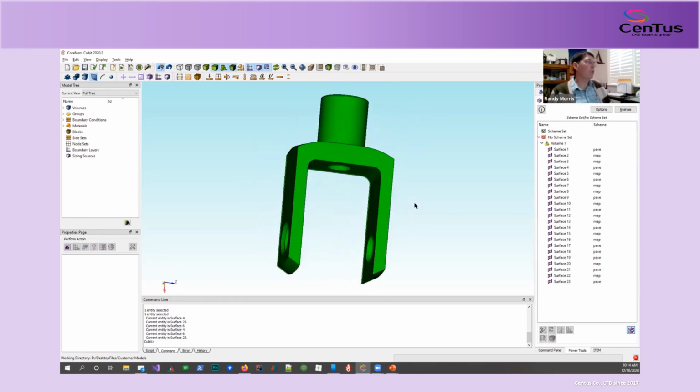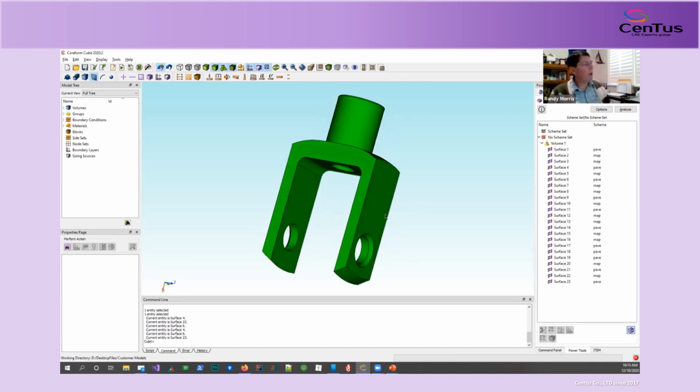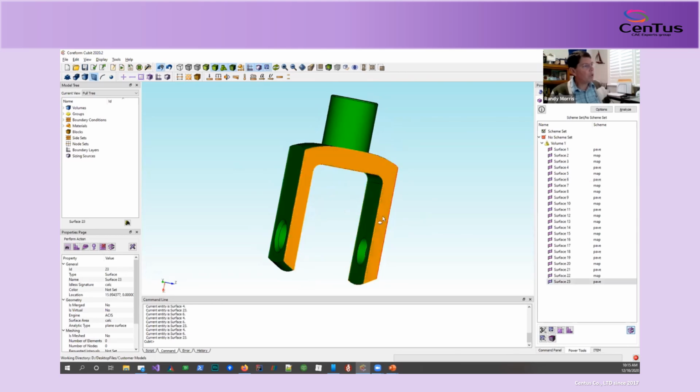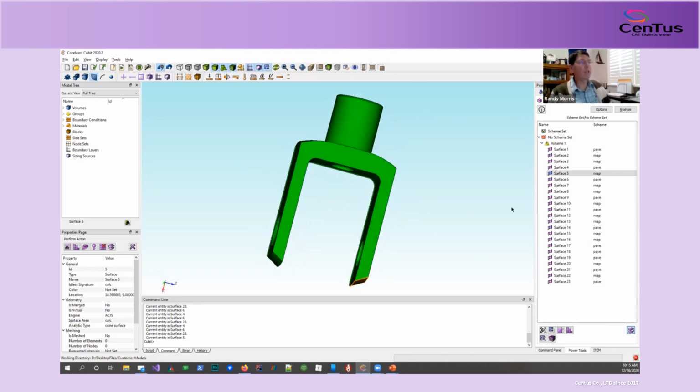And in a subsequent step here, we're going to isolate some of these parts by cutting them and making smaller volumes that can be paved and then swept, right? So in the end, I'll cut things here so that this surface can be paved, this surface can be paved, and this surface right here, which is a linking surface, as well as this one down here, can be mapped, right? It has to be that case. So anyway, let's go back to this tool.